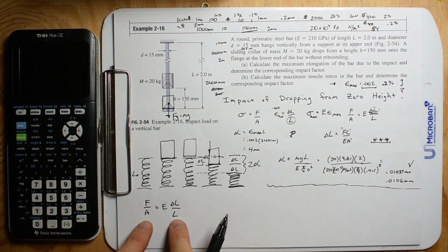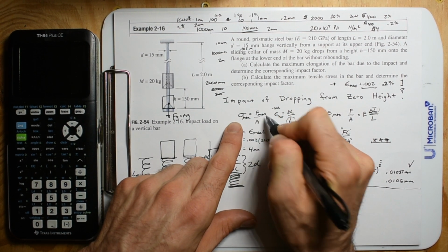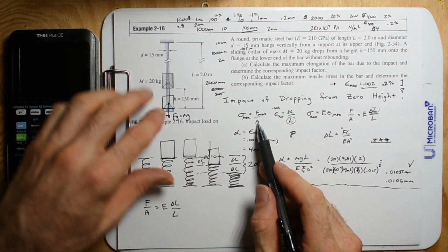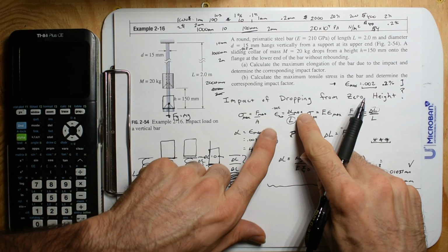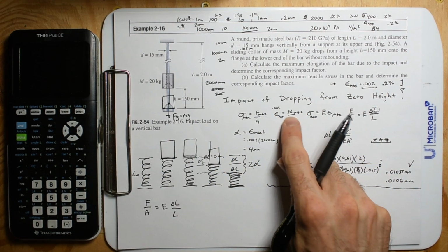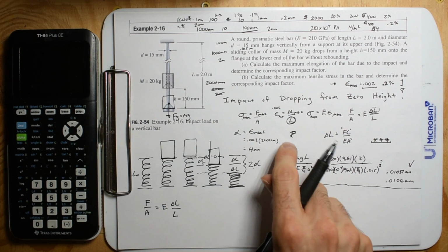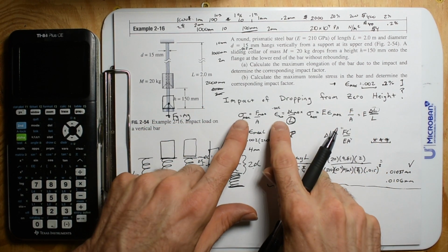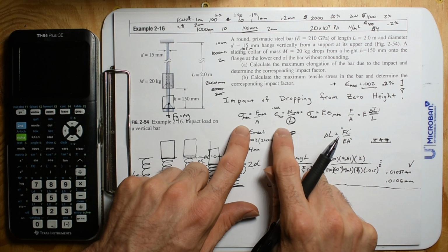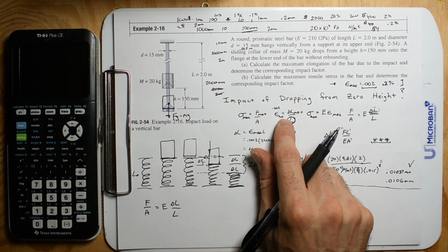Now of these, what can we put subscripts on? Because here, we can say, hey, this is max and this is max. But we don't put a subscript on area. That's already given for our problem. Same here. We can put max change in length, max strain, and then here's our length. So that's going to be the trickiest thing doing material mechanics, is knowing that these can be max or these can be less than max. Maybe allowable. And anywhere in between, from 0 to max.